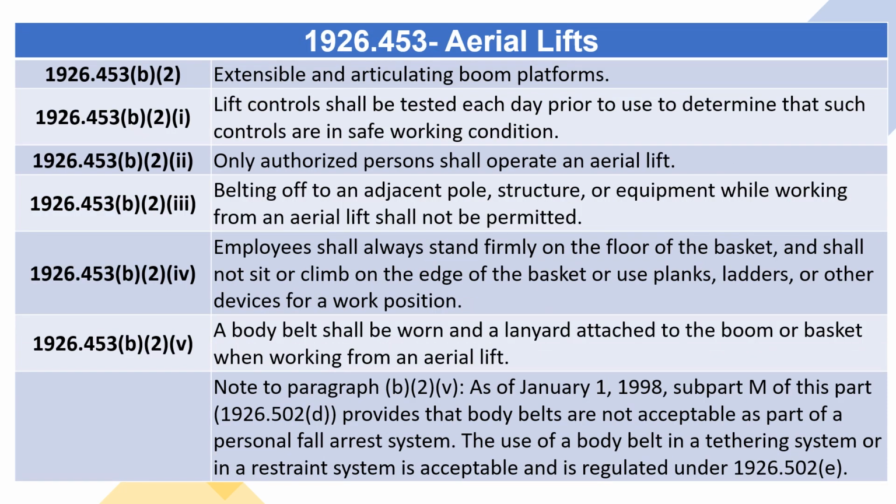1926.453(b)(2) Extensible and articulating boom platforms. 1926.453(b)(2)(i) through (xii): Lift controls shall be tested each day prior to use to determine that such controls are in safe working condition. Only authorized persons shall operate an aerial lift. Belting off to an adjacent pole, structure, or equipment while working from an aerial lift shall not be permitted. Employees shall always stand firmly on the floor of the basket, and shall not sit or climb on the edge of the basket or use planks, ladders, or other devices for a work position.